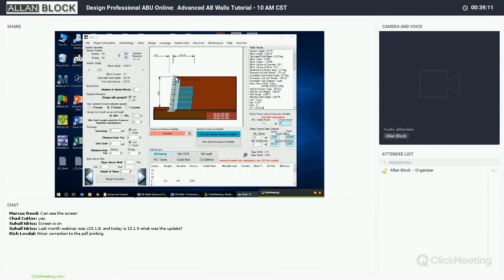Notice though, and you can see this bright red, that the overstress, block pullout, soil pullout, those values do not apply for compound composite structures. We are relying on internal compound stability to check. So I would just run this analysis real quick to make sure I'm not having any problems. So I go ahead and hide this, and technically I'm looking at a structure now that has a gravity wall on top and then a reinforced structure below. All safety factors are being met, so we could make a judgment that this could work just fine.